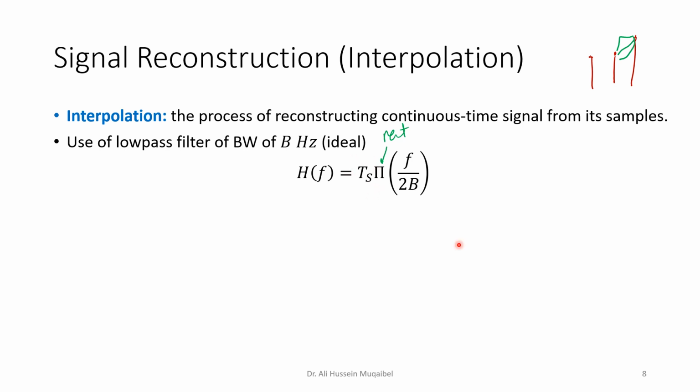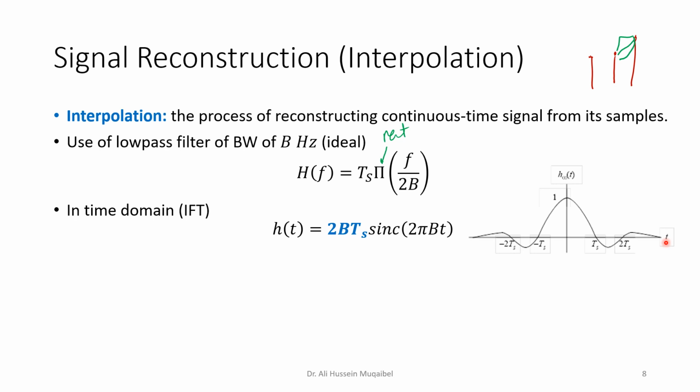So let's go now work backwards. Let's go to the time. If you go to the time and use inverse Fourier transform, you'll find that the inverse Fourier transform will be a scaling factor by sinc, which means that the impulse response should be sinc, which means for every impulse we should have a sinc. Now, this is how the sinc looks like. The simple sinc would look like.